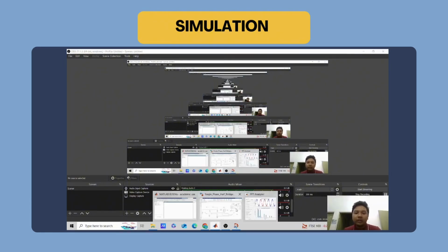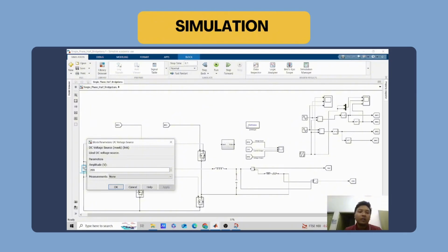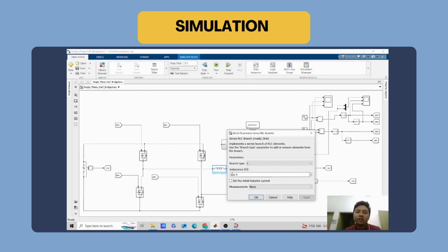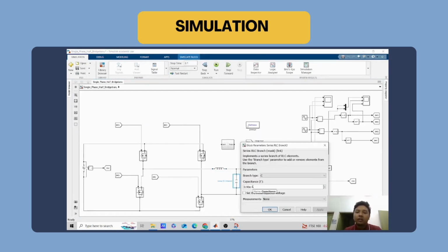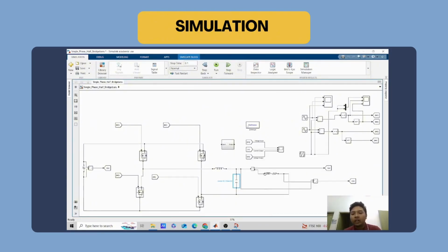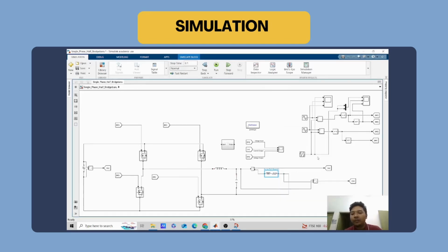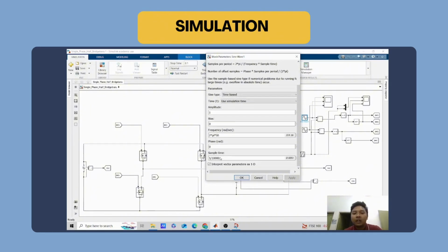So my part is about the simulation. As you can see here, this is the circuit for the SPWM single phase full bridge with the LC filter. Before we run the circuit, we must input the value for the DC, which is 269 volts. For the filter, the inductance is 31 exponent negative 4, and the capacitance is 0.9 exponent negative 6. For the load, the resistance value is 14, and the inductance is 0.3 exponent negative 3. For the sine wave, the amplitude is 1, frequency 50 Hz, and sample time 1/10,000.